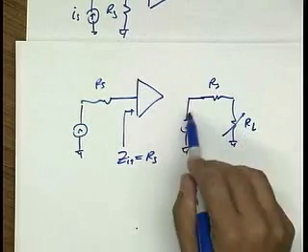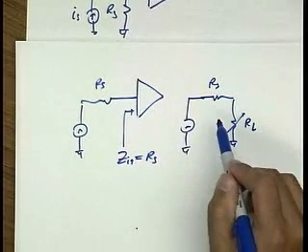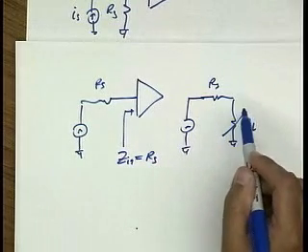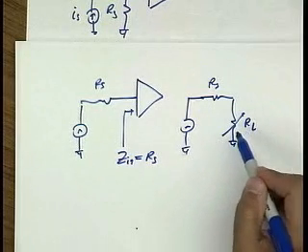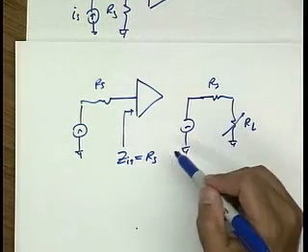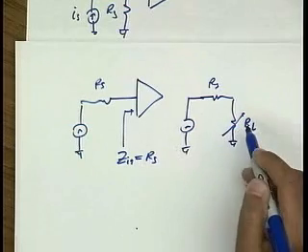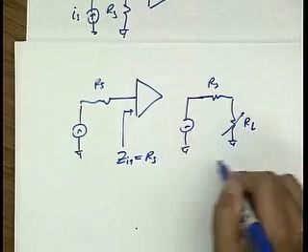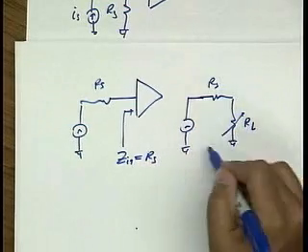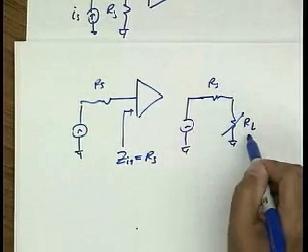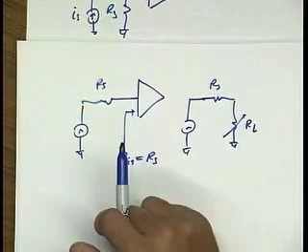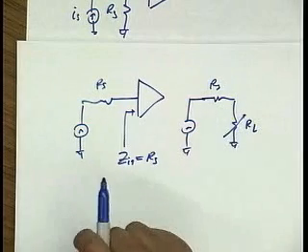If we're talking about transferring the maximum voltage, then we'd make RL infinity. That's a voltage amplifier. If we want to transfer the maximum current, we make RL equal to 0, and we maximize the current in the circuit. But to transfer the maximum power, we make RL equal to RS. And that's a simple two-line calculation.